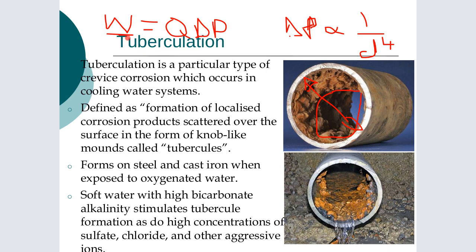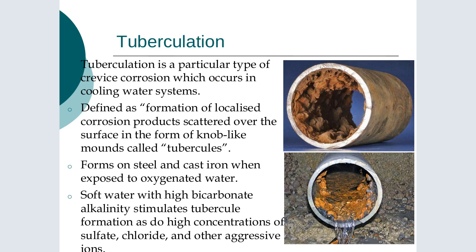And furthermore, when we get to the pumping section, you'll see that, particularly if it's a centrifugal pump, you'll have designed it to be working at a particular sweet spot in terms of efficiency. And if you change the resistance of your system, which would happen here, you end up shifting that off its ideal operating point and best efficiency point. So that means your pump is working less efficiently. So on top of this, your actual electrical work is linked to the efficiency of the pump, and that will change.